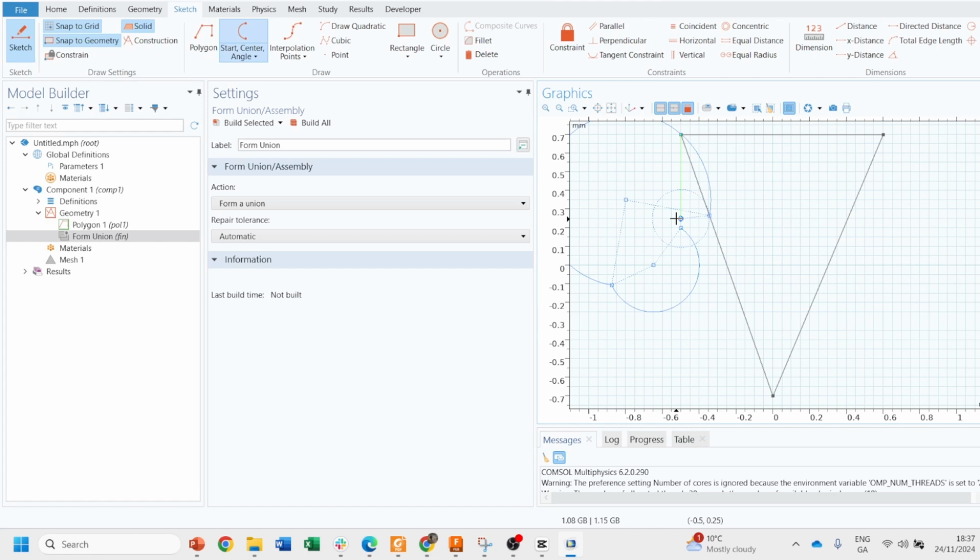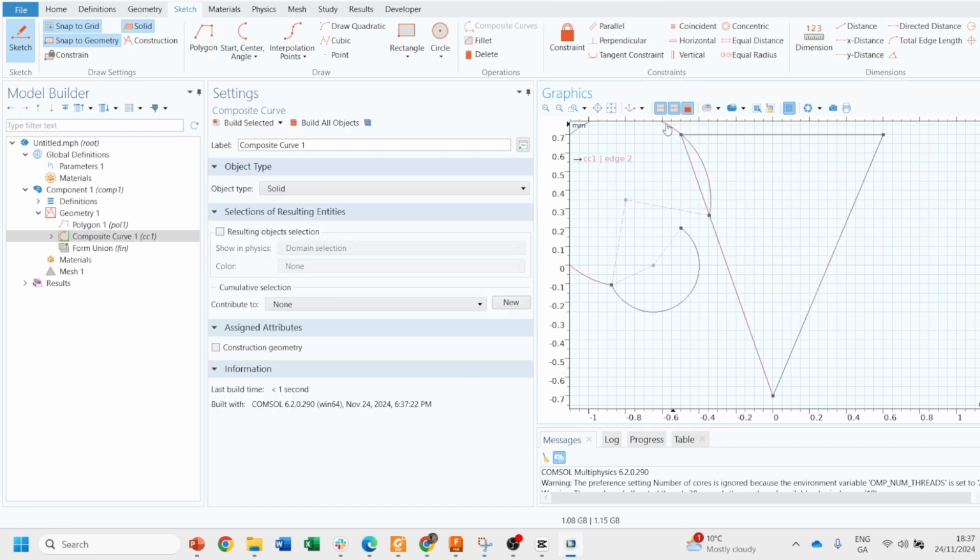It's not mandatory that you have to close every point for the design to be formed. You can just right click on the last point. There would be an option of finish circular arc, then you can finish the design there only. So just click on finish arc. You can see here also the design is formed. Later, if you want to create a closed object, you can just click on the polygon, or you can join 2 points later. Those parts can be done later as well. So these are the different options.